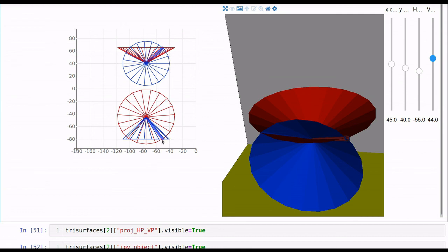Similarly here in HP, at the intersection of this line and this, we are taking B's HP projection, and here also the intersection of the circle and the line, we are taking the VP projection of point B. So with this AB constructed like this, it satisfies both conditions: it is inclined at 30 degree with HP and also 45 degree with VP. With this I'm going to conclude this video. We will go further with the presentation.